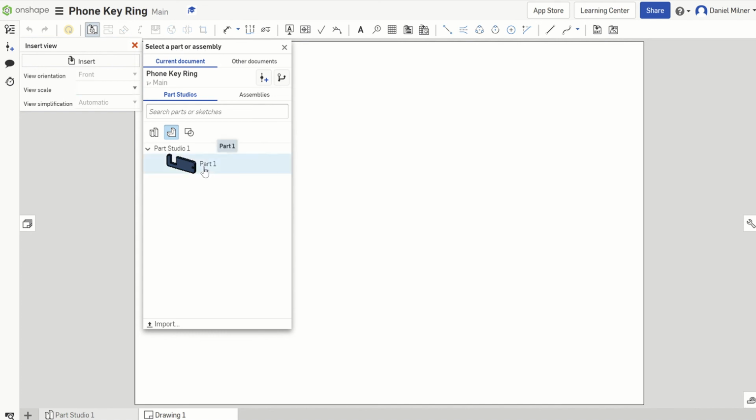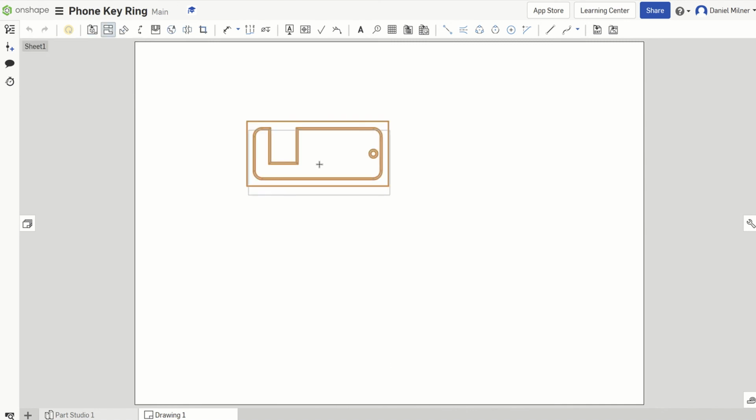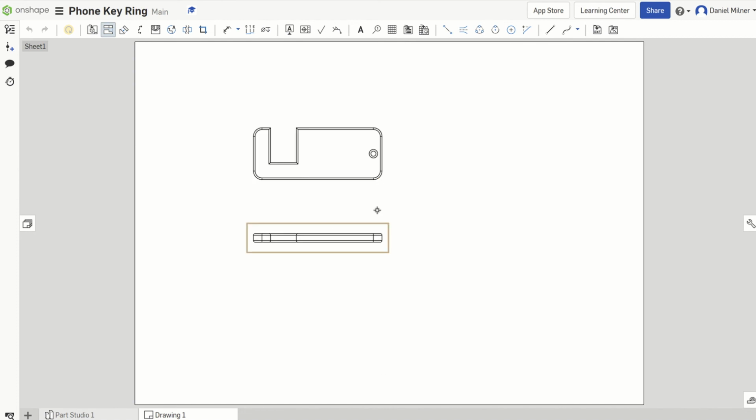So I'm just going to left click on this, and when I left click on this, I have the outline of my elevation. To simply drop that where I want, we'll say this area of the page, top of the page, left click. When we left click and come straight down, we should be able to generate a view of my plan. So I'm just going to left click again, and those are the two views generated.